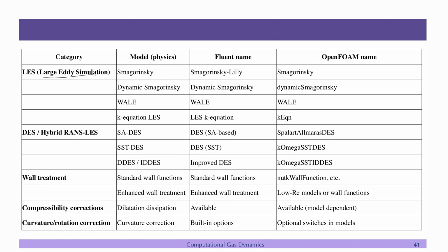Okay. So, for the smaller eddies you have to use some model, just like you use the turbulence model for every eddy in the turbulence in the RANS. In the LES you will be using a model basically for the very small scales, and effectively you are using filtered Navier-Stokes equations. In the RANS you basically change the equations itself, but in the LES we use a filter. That means, if my eddy size is smaller than this, then I am going to model it, otherwise we are going to simulate using the exact Navier-Stokes equations, right.